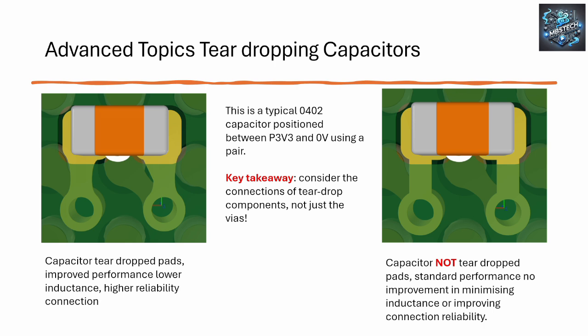Okay. So this is the end of this presentation. So in conclusion, selecting and placing the right capacitors is essential for maintaining power integrity, ensuring reliable FPGA operation. Decoupling capacitors provide transient current to prevent voltage fluctuations, while bypass capacitors filter high frequency noise to maintain clear power lines.